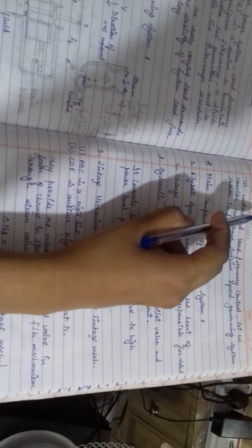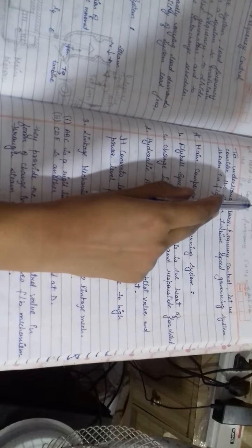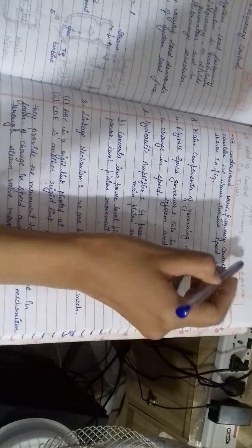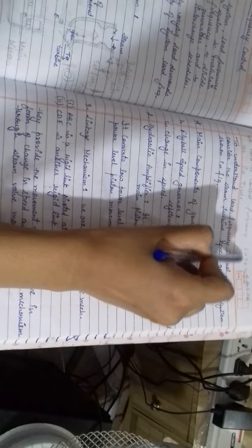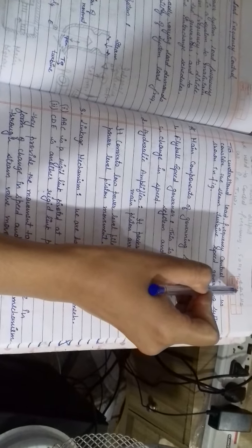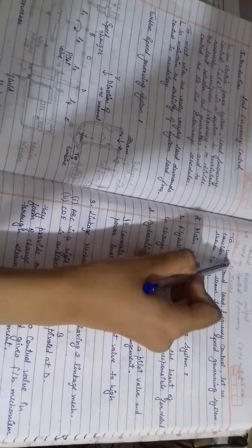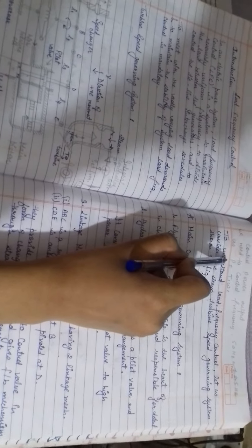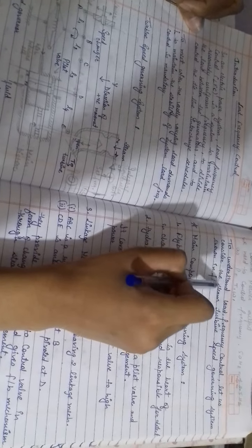First, we need to understand the concept of the turbine speed governing system. We need to control the power output. Our aim is to control the power output, so we need to control the frequency. Generally we give 50 hertz frequency, and we can allow changes in the frequency of plus or minus 0.5 hertz. To control the power output, we need to control the frequency also, because we know that power equals torque into omega. So first we need to understand the components of the governing system.